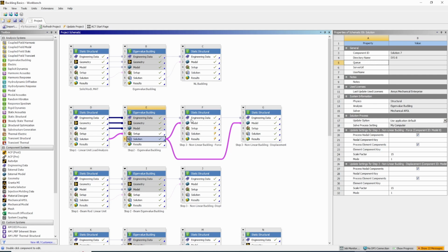I will be using the nonlinear structural steel model here for this analysis. The key point to note here is that what I'm importing from here is the deformed model at mode 1. So this is what you specify here. Just click on this, and you will get your mode 1 and then your scale factor.